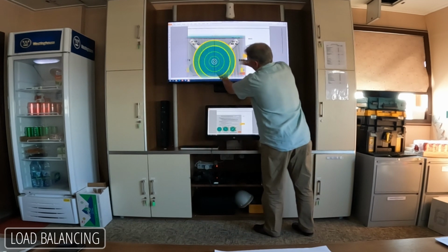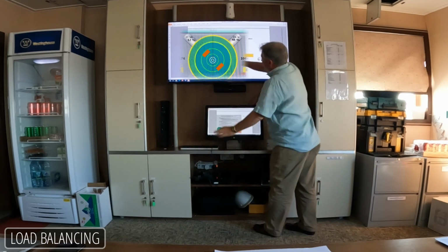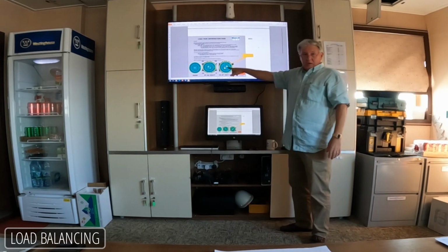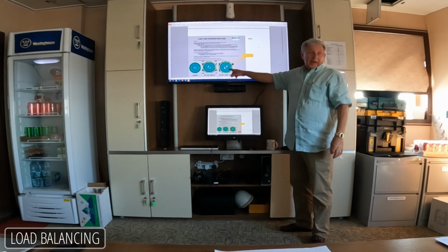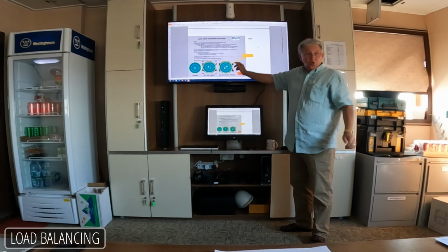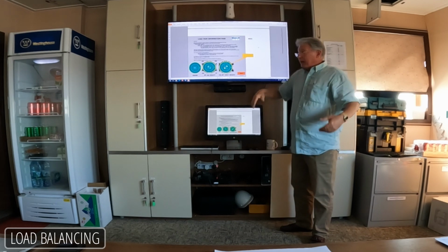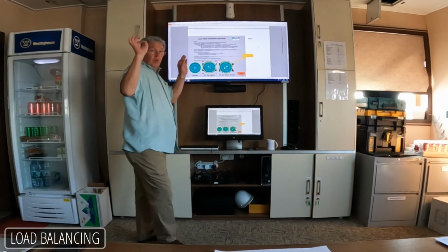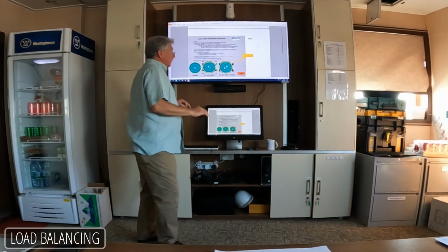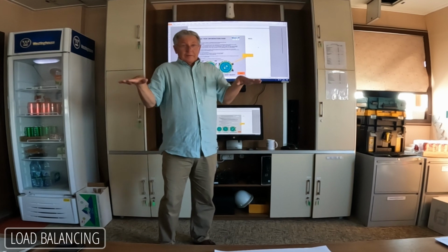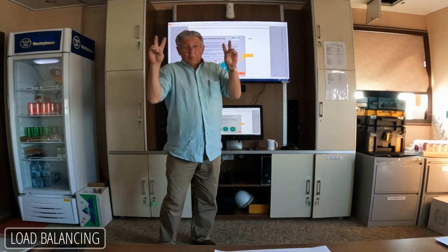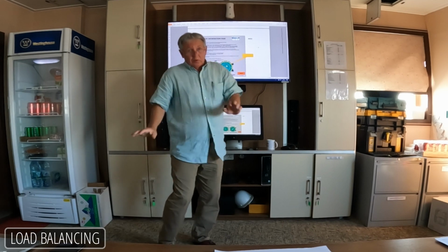This guy here is very heavy, and now there's red color coming. You don't want that. If you get red color, you're way out of whack, and there's too much weight on one diagonal. Now you will see this in preload because we do it on purpose. That's a different story. This is the jacking of the boat, right? Because when you're preloading, 2 legs are staying still, so they're really at holding, or in some cases storm holding, for that moment while you're doing the preload.